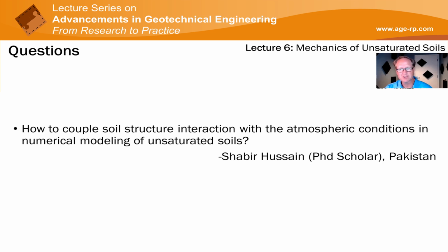How to couple soil structure interaction with the atmosphere conditions in numerical modeling of unsaturated soils? A great question, because the atmosphere controls how much actual evaporation happens. A lot of times in seepage modeling, we just model a certain flux condition or we model potential evaporation, where what you really want to do is model actual evaporation.